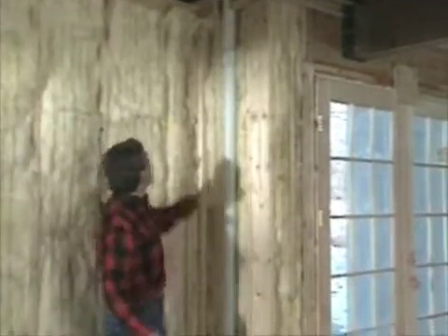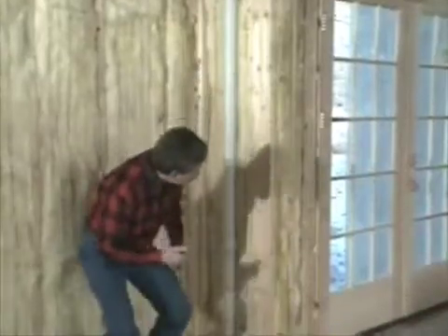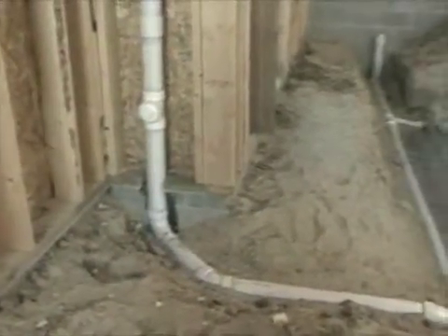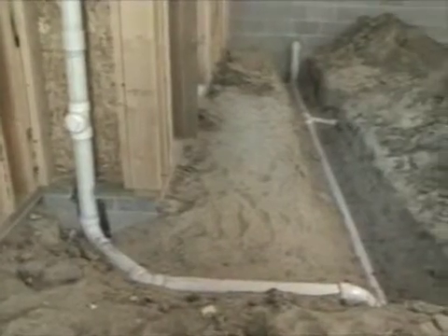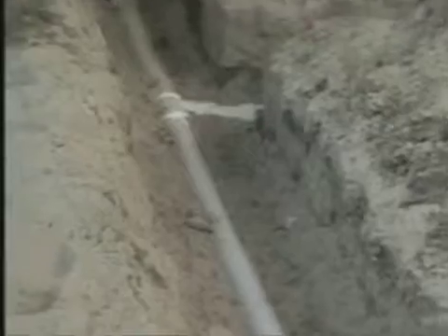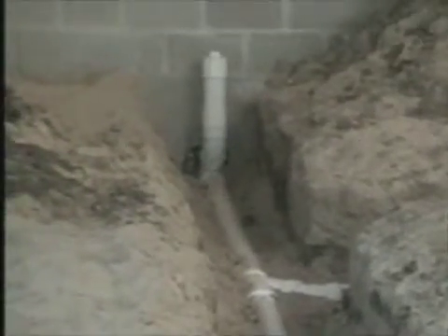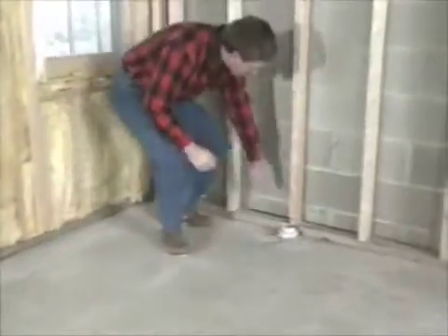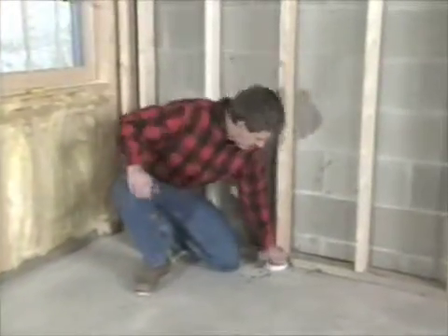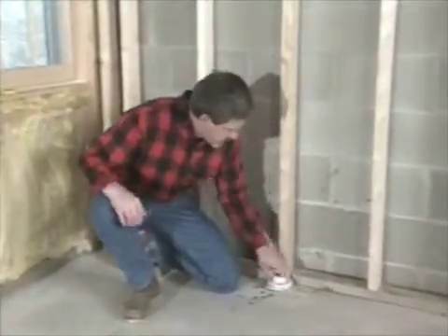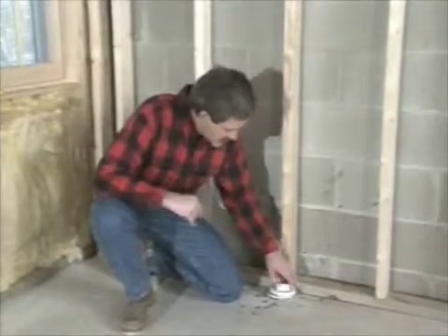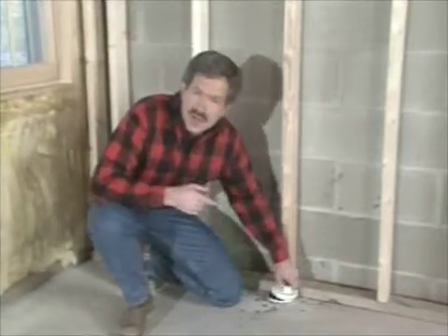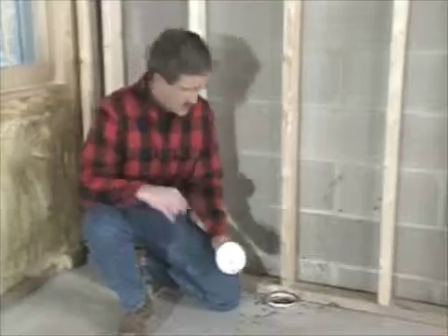Down here in the basement, the pipe continues through the wall and then goes underneath the slab. Before we poured the slab, we shot some footage so you can see how the stack ties into the main house drain. That's the 4-inch pipe that drains all the house systems. It carries waste outside to a septic tank or a municipal sewage system. The slab covers up the drain here, but this cleanout plug is still exposed. We can unscrew this here, and it allows us to clean out any clogs. Now, these are required at the base of all stacks and along horizontal runs.